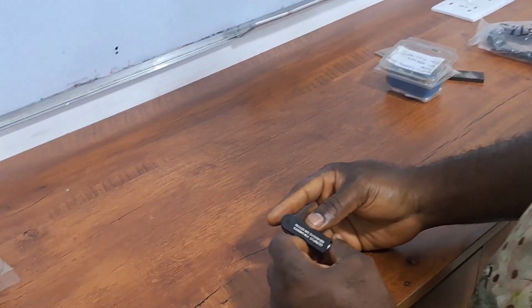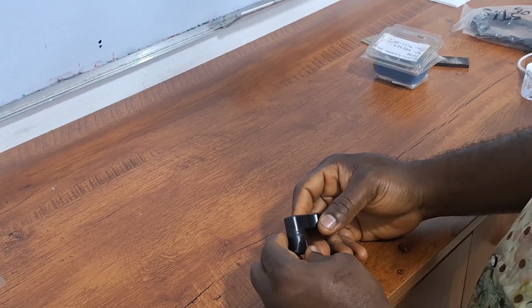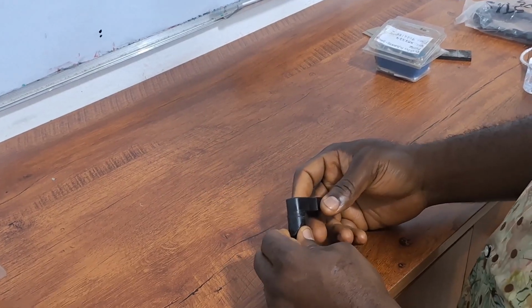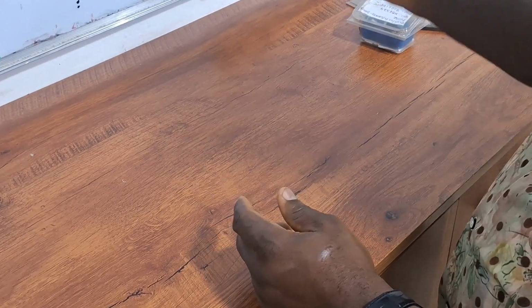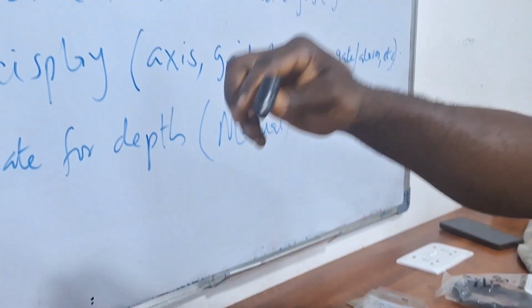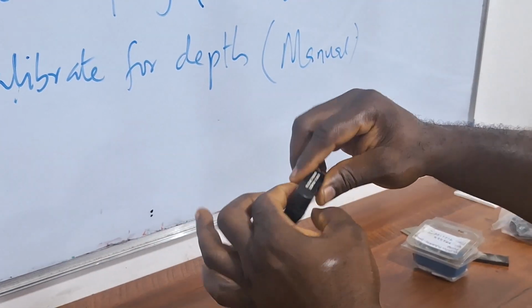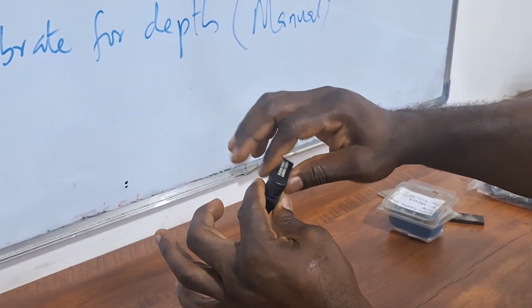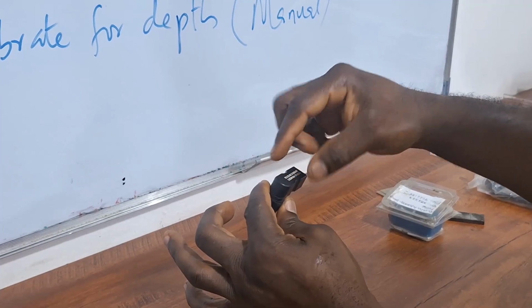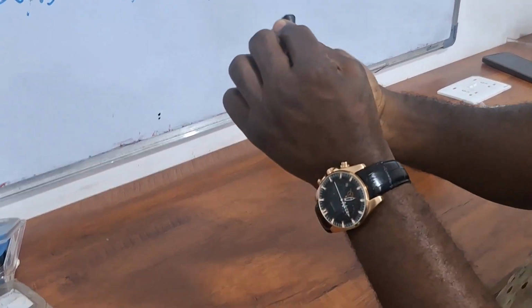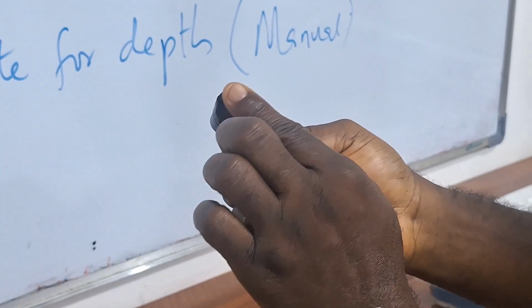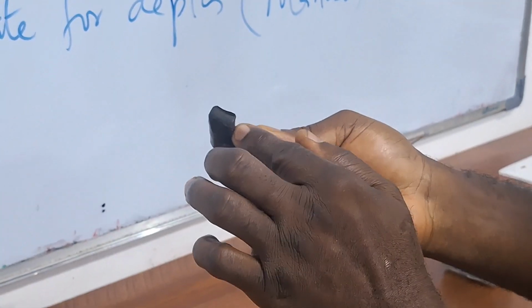The next probe we'll be looking at is the weld probe. They come in different designs. This one is the angled type, where you can also see the depression, by the curvature rather, where you can place your hand for your scan. It also has a bridge design where you have a coil here and another coil here.